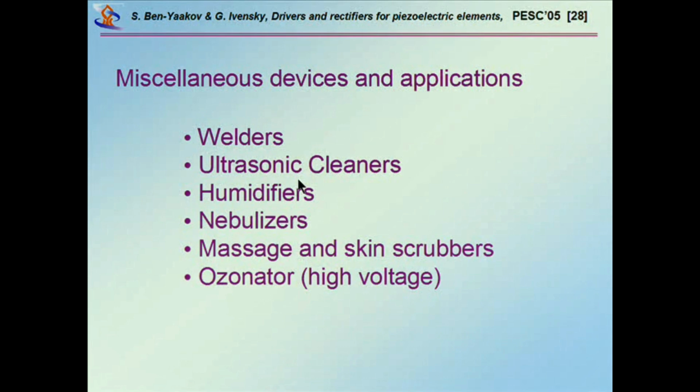And you usually couple them mechanically to a tip, and then you can do very nice welding, for example, for bonding wire into a solid material, or even, in fact, microelectronics, they do it. So the tip is connected to this piezoelectric element, and it is run at high power. I'll have some electronics for these later on when we go into the electronics part, but they are used and they are fairly high power. Right? Yes, please. I have another question or comment.